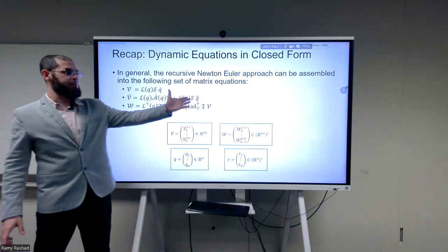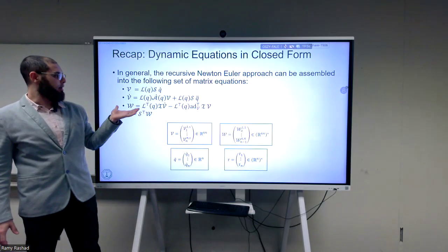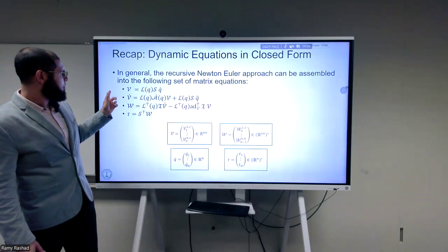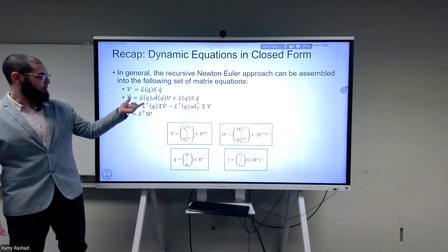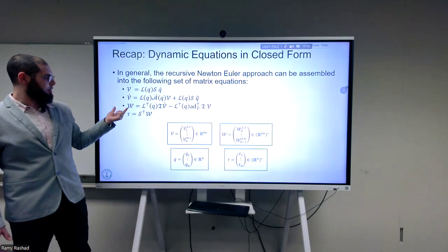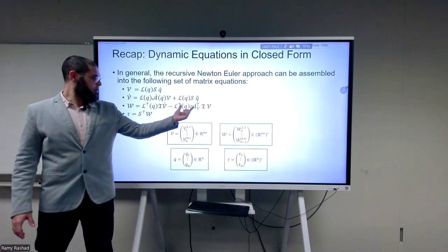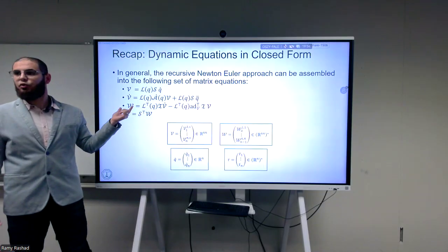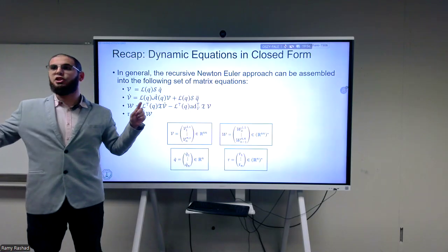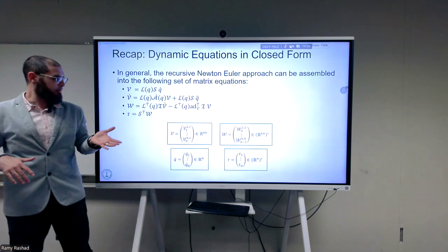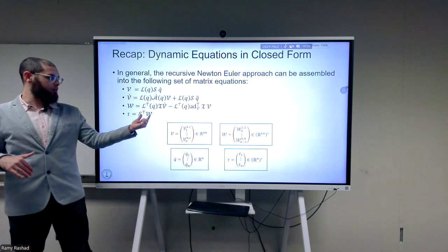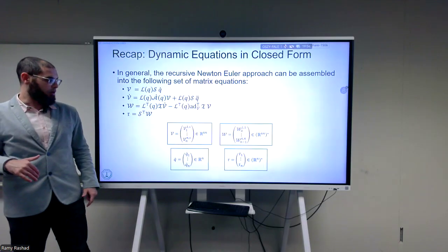And the V dots, I can simply compute them in an expanded form. I think there's... No, it's correct. So we have this expression, and then afterwards we have this equation, which is for the wrenches, which consists of all of the inertias, they appear here because this is nothing else than the rigid body equation, just stacked over each other. And I have here all of the actuation torques that come from these constrained wrenches.